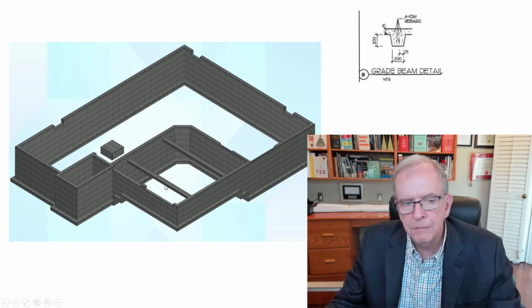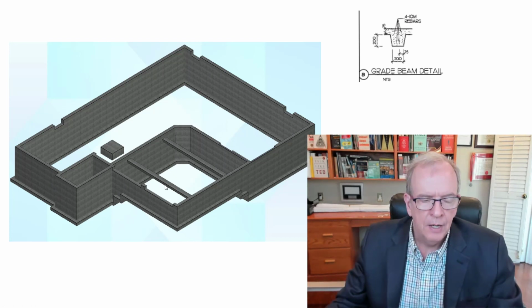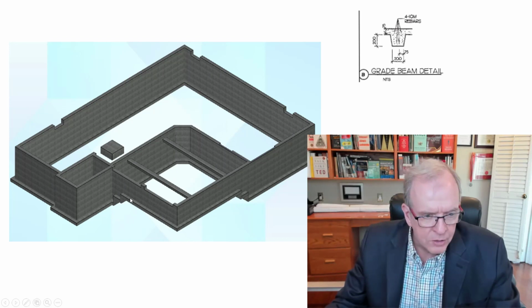And these grade beams are there to help prevent the slab from sagging. From that perspective, it's always a tricky sort of design when you get into those kinds of areas. The key is to have this really well compacted in the interior part here. Now you can also see this is stepped, so that's what I was referring to.